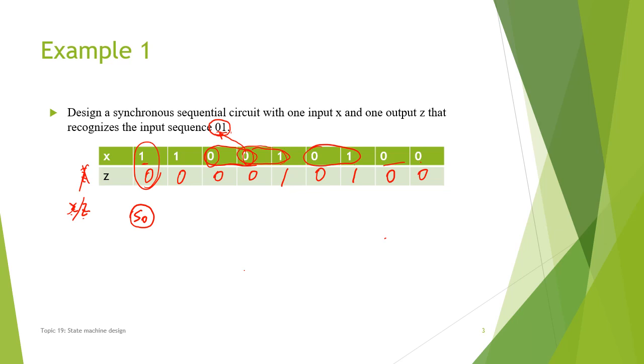So, which means we didn't detect the first bit of the pattern. Okay, which means we don't make any progress, so we need to stay in this state. Make sense to you? So which means 1, 0. So x equal to 1, and we are at state 0, S0, the first state. So nothing is going to change. Then we will wait till the next bit of data.